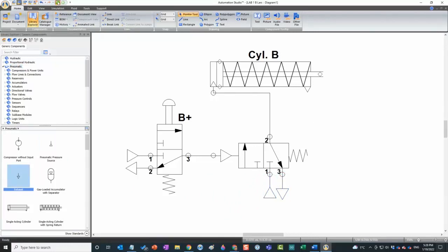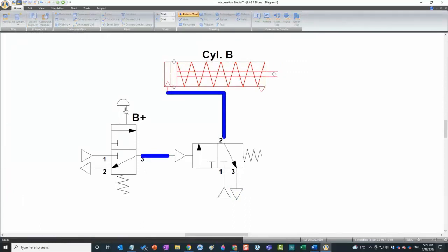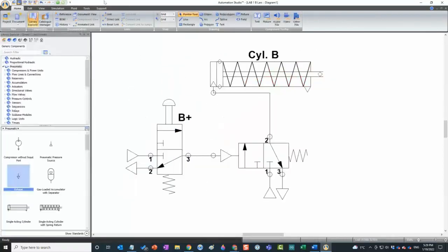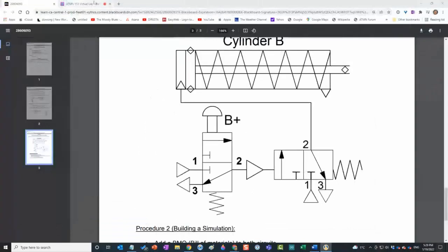Let's run it again and see what happens. Nice. When I press play, look at that. Cool. So I want to make sure that you guys understand how easy it is to draw these things. It's really about drawing your first one, putting a lot of love into it, and shrinking those fonts down. The reason you shrink the font down is because it gets in the way. If you want to click on something to move it or change it, that large font area, even though the word is small, is going to get in the way when you're trying to select things.